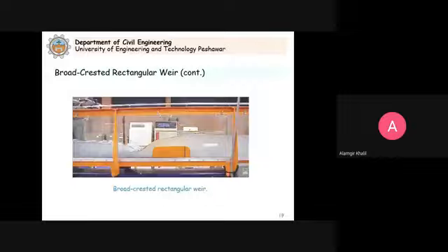Here you can see we have this normal depth. Then the depth reduces to the critical depth here, and this is due to the damming action. Immediately downstream you see the depth is less, this is the supercritical depth. You can see the supercritical depth immediately downstream, and then this is the hydraulic jump. So it will dissipate the energy here, and then after that, from this lower depth, it has to go to the normal depth, and the water will continue to flow in the channel.